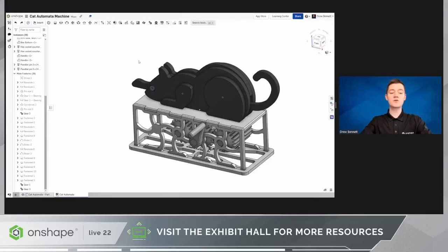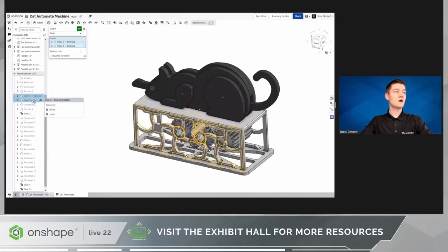To set up a mechanical relation, choose one from the top toolbar and then select the mates with the correct axis of movement. A gear relation is a really easy one to show off, and I need one, so let's put it in there. It's going to take 2 mates that have a rotational axis to them. So I will first use a cylindrical mate, then a revolute mate. These 2 mates are currently holding the gears in place.